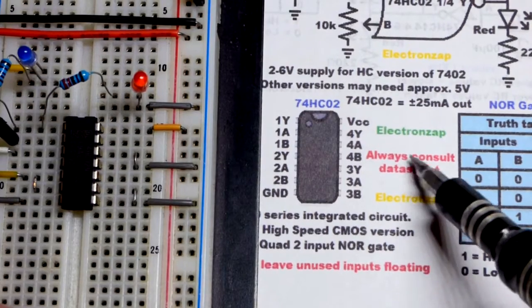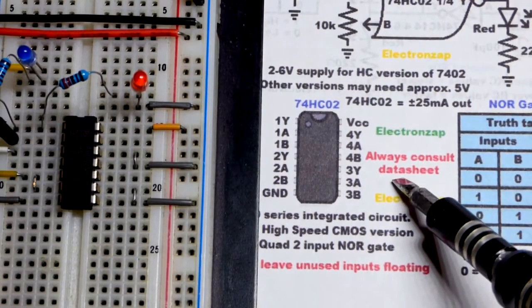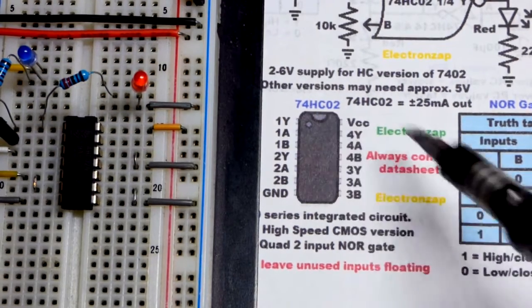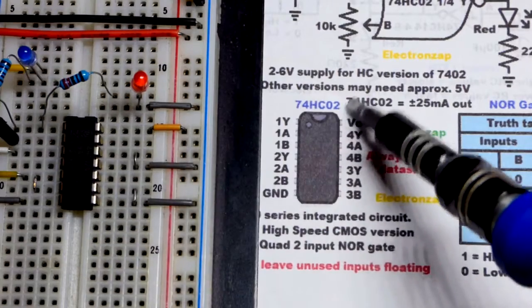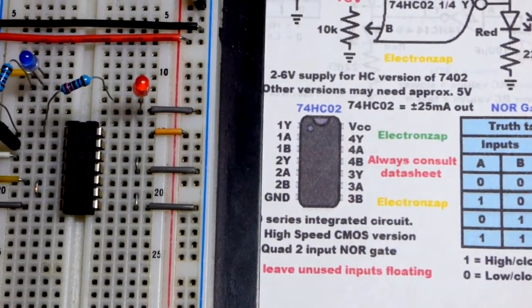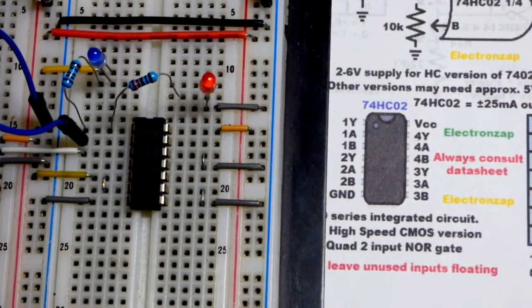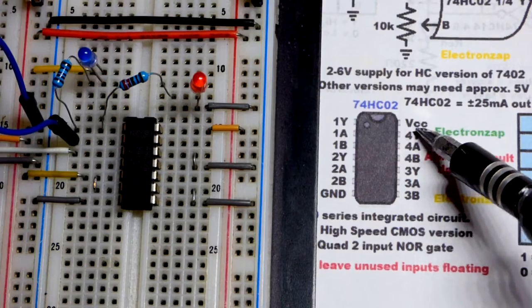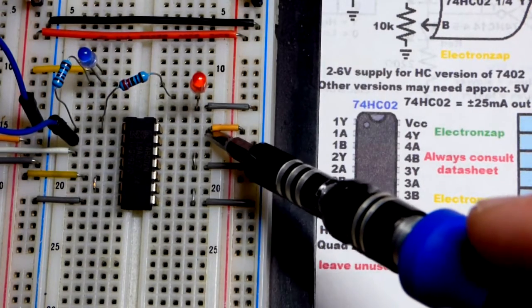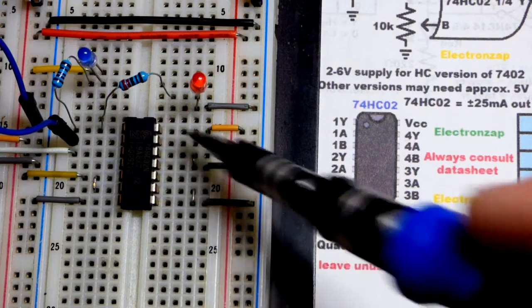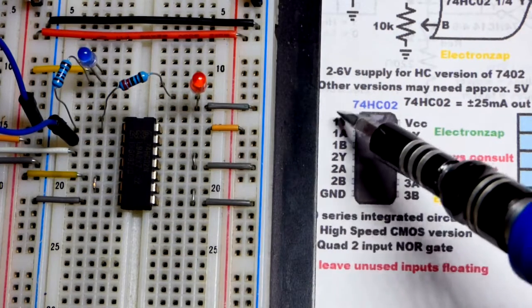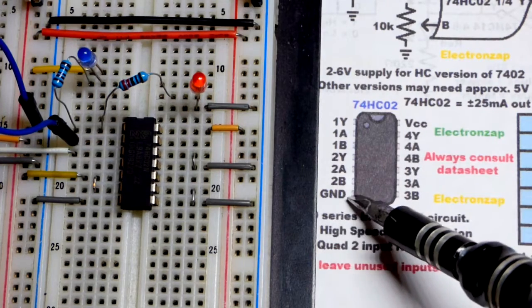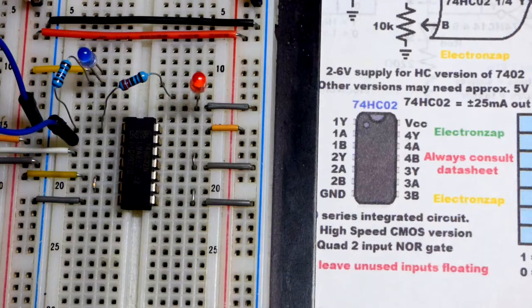So now we come to the breadboard, and just in case I forgot to mention it, I think I did, always consult the data sheet of whatever part number you are using. Look this up. I'm actually using the N. There's an N after the number there, but that's not terribly important. That probably means it's slightly improved from the basic version. But in any case, we need to power the integrated circuit, so VCC is the positive supply. As you can see, we've got a jumper to the positive supply there, going to pin 14 up there. Pin number 7 is down on the bottom left, so we have 1 down to 7, and then 8 working our way up to 14. So pin number 7, ground, we connect to ground again.